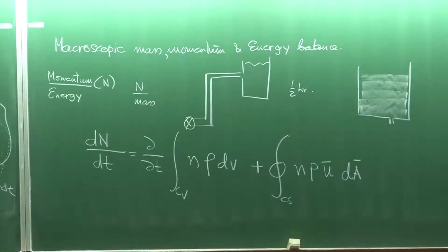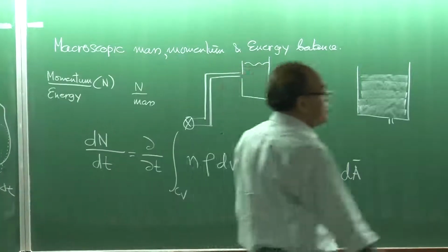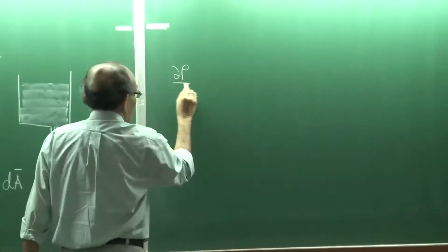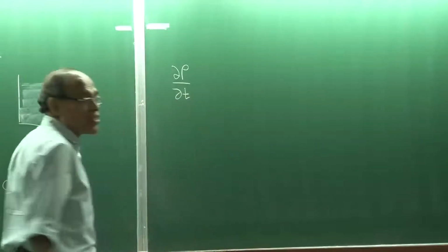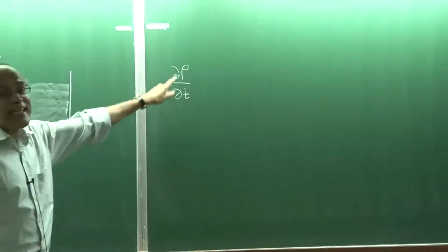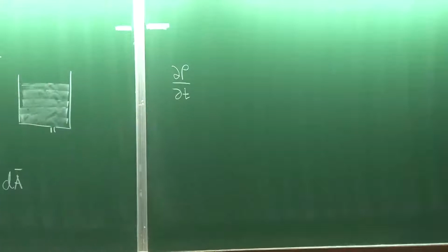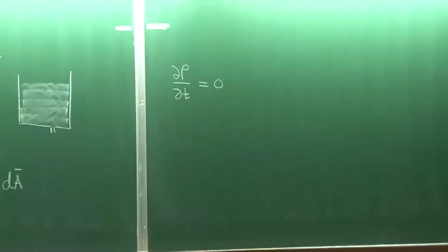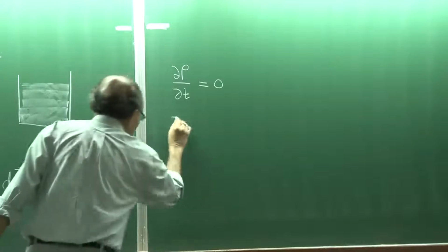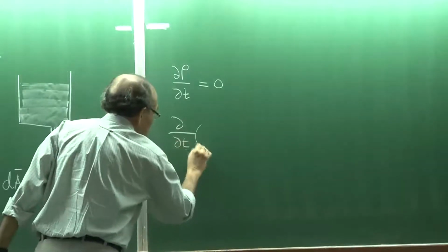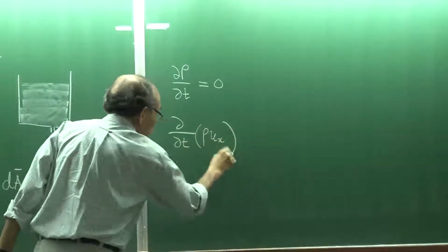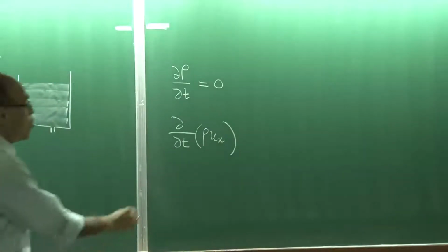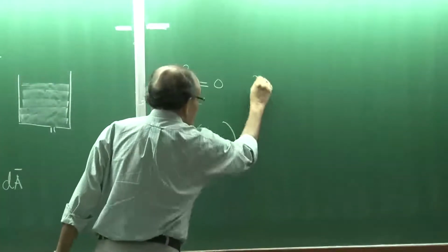As you have seen, this d rho term we have set to zero when writing the momentum conservation equation. We said that nothing changes with respect to time, and hence this term would be zero even for a compressible flow, if the flow is steady. So, this term appearing in the continuity equation, or in the momentum conservation equation, for example the x momentum conservation equation, will all be equal to 0 for a steady state problem.